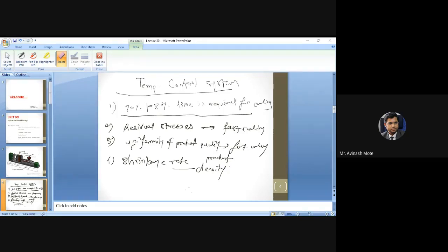Right. So now see, there are so many cooling medias that are not part of our syllabus. But if you study metallurgy, they have discussed them in detail. Like air cooling is there, oil cooling is there. Basically, this process is called quenching in metallurgy. So air cooling, oil cooling, oil bath or water bath, anything. Getting it? Okay. So this cooling rate will depend on the cooling media also. That is called the quenching media.